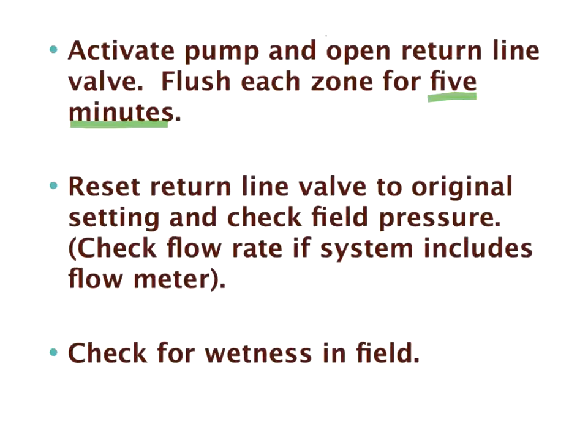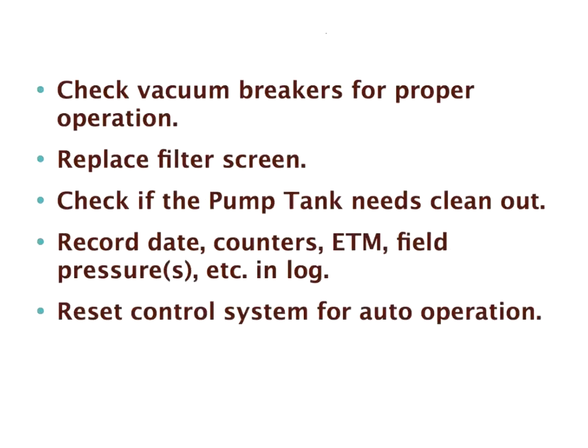Okay, walk the field. Nothing like walking the field. Check your vacuum breakers, as we spoke about. Replace filter screens or discs. Check if the pump tank needs cleaning. Record everything. The date, the counters, I don't know what ETM is, it doesn't matter. Fuel pressures and etc. Reset your control system for automatic operation.